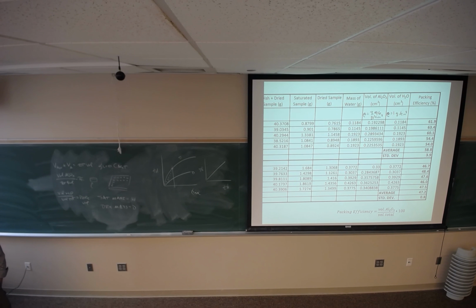I would like you to figure out, as part of your experiment, what that time interval would be after you cast before you measure. If you wait too long, your densities will creep up. So you can show what that weight loss is as a function of time, because that's an important part of our experiment. And then the question is, how do you construct these experiments to do extrusion, slip casting, and tape casting? That is your job to develop.